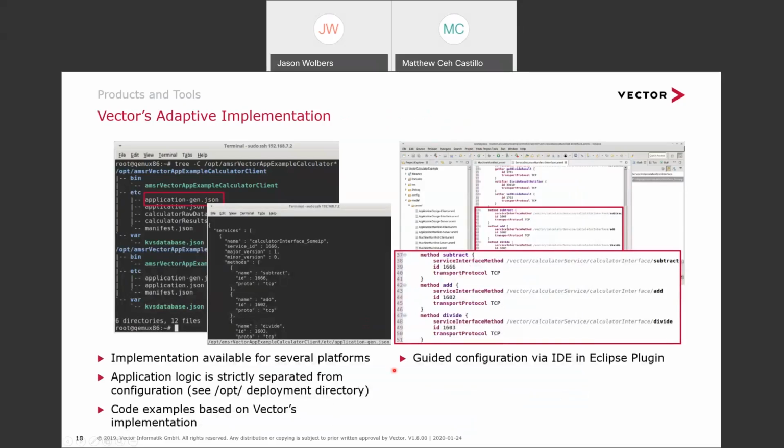All right, so now those of you that may be familiar with AUTOSAR Classic, you're probably familiar with DaVinci Configurator and DaVinci Developer, which are Vector's tools for configuring and designing for AUTOSAR Classic. And those are very GUI driven, very point and click, check boxes and pull down boxes, and drawing stuff in the interface essentially. So one big difference here with adaptive is we've gone with more of a coding approach using a shorthand scripting language rather than a GUI-based approach.